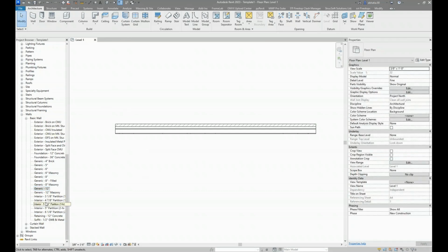So that's basically what I do. I review my walls that I have here, see what I need to keep for my typical projects. I will not get rid of it just because my immediate project does not need it, right? This is a template. We're trying to set it up to be able to accommodate every project that we might get. Obviously, we cannot cover every single situation. It's good to evaluate what is your typical project, what would you typically need to have in there, right?